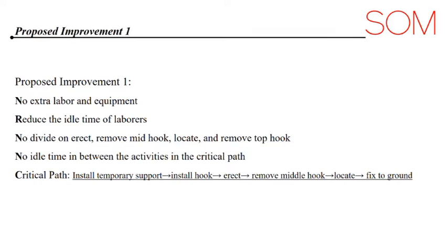First principle, the erecting time, hook removing time, and locating time are non-dividable in the construction site. Secondly, there is no idle time in between the activities in the critical path. And the last principle is, works that are dividable are assigned to more laborers to reduce the idle time. So generally speaking, our proposal number 1 is based on existing conditions and rules, but only trying to rearrange the resources.